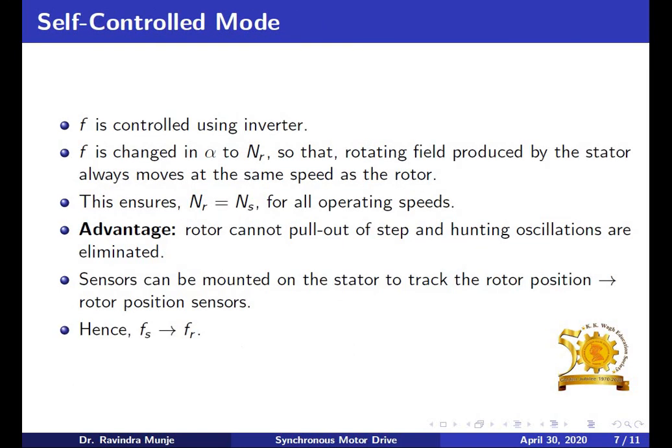Now we'll go for the next method, that is self-controlled mode. In this case, the stator supply frequency is changed using an inverter whose SCRs are fired in sequence using the information of rotor position or stator voltage. Supply frequency F is changed in proportion to rotor speed,